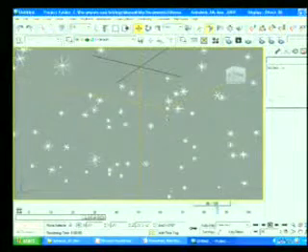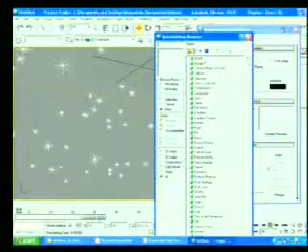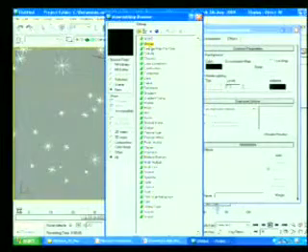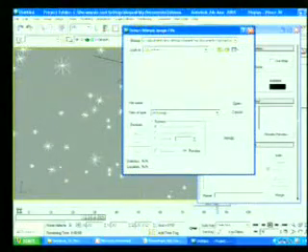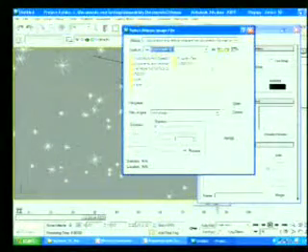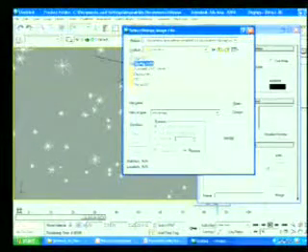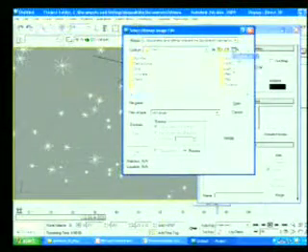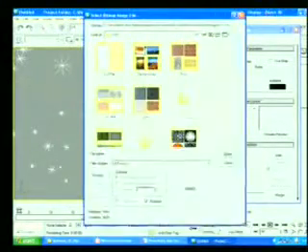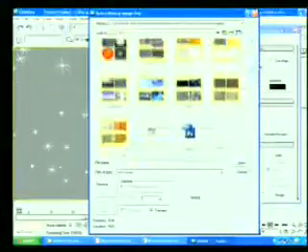And we can put an image behind this snow. Open the environment effects, environment map, bitmap, go to the drive and the maps, by default maps, which come with the software.